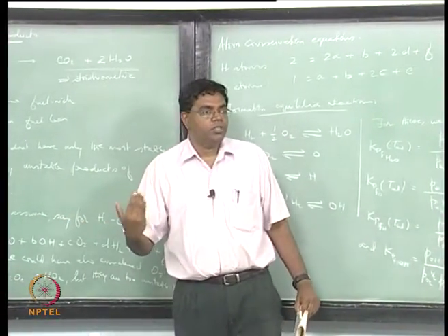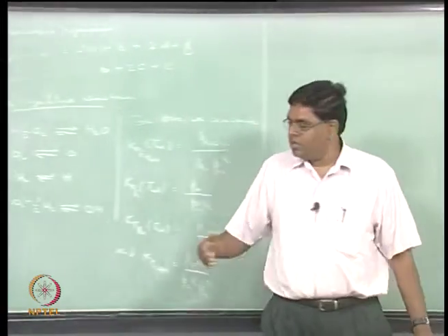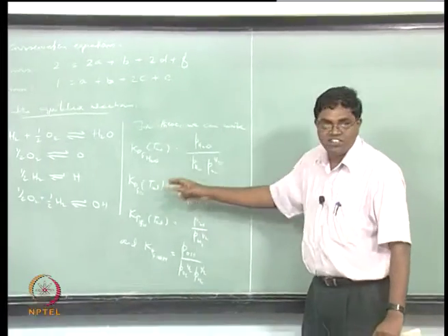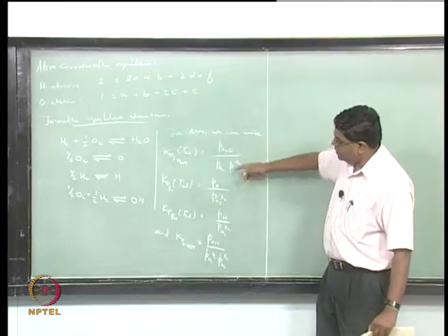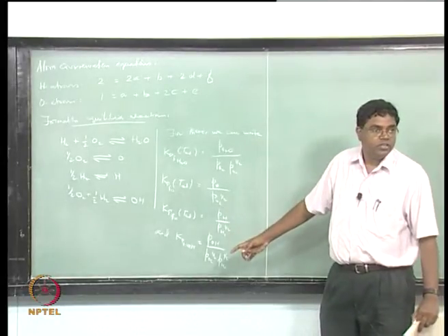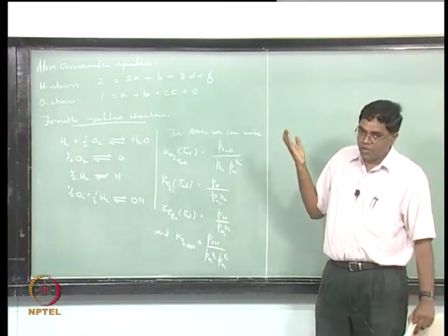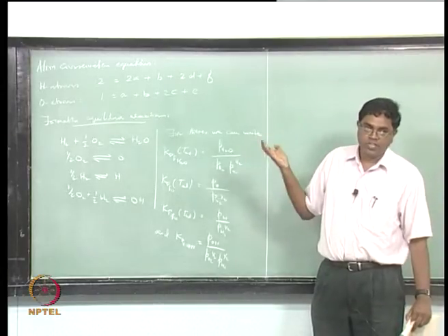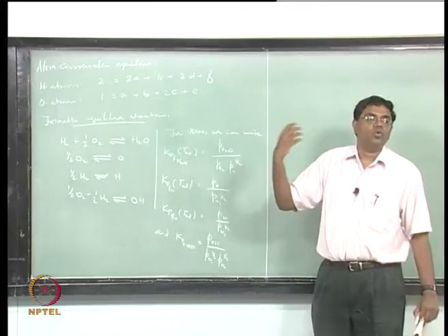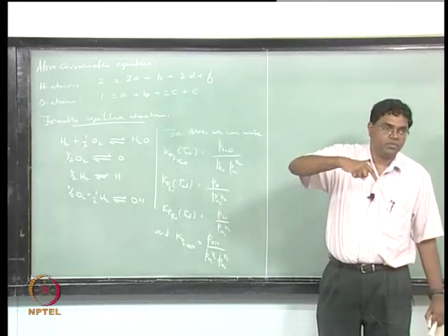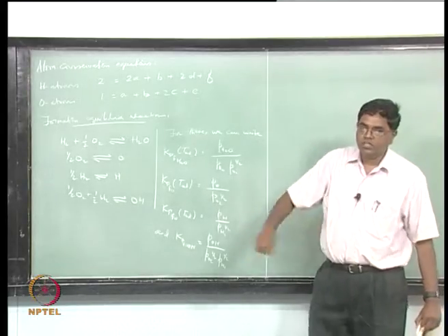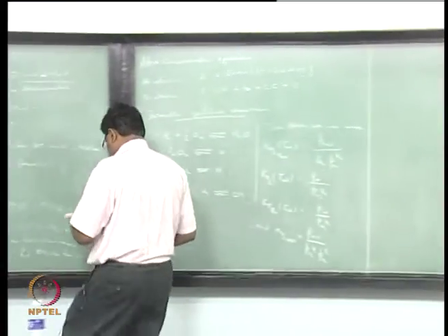So dependent upon the pressure and dependent upon the Kp equations, the proportions of these are going to get altered, okay. Therefore the pressure is going to influence the existence and the amount of the unstable reactants that will soak up some heat and alter the adiabatic flame temperature of the products. You see, that is how the pressure is essentially coming into picture.